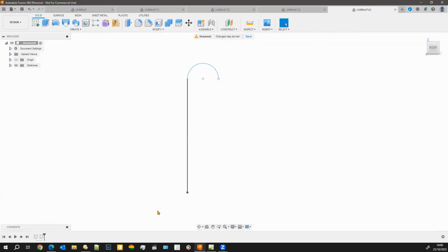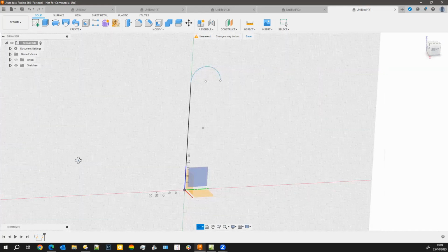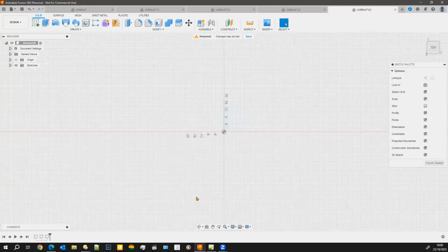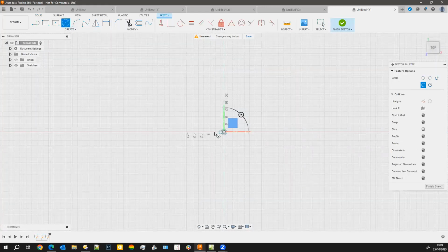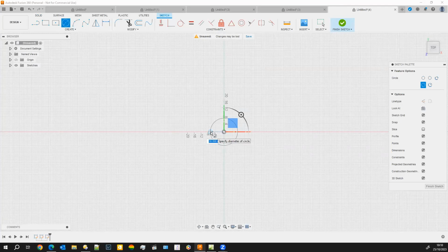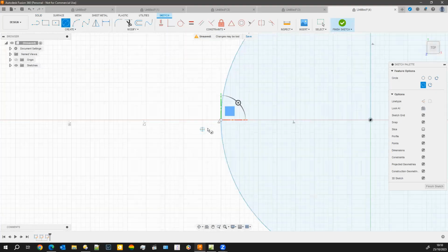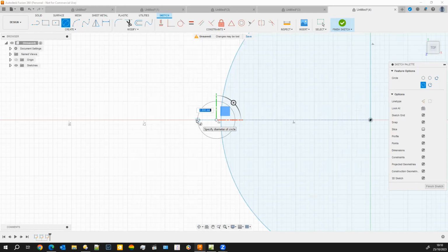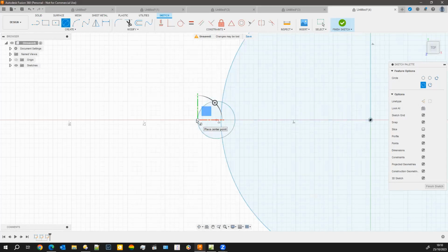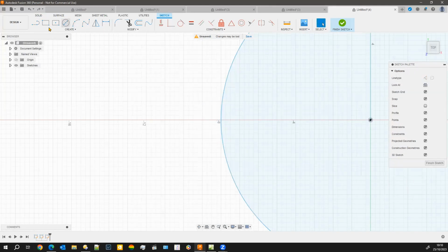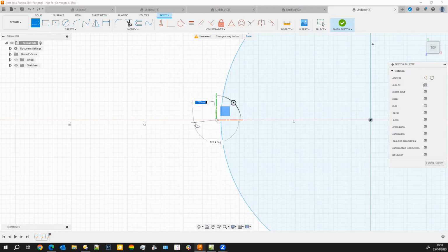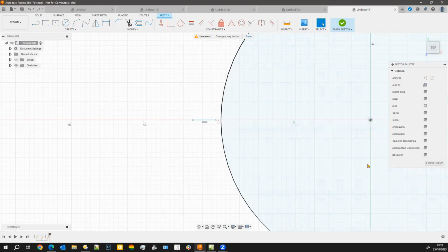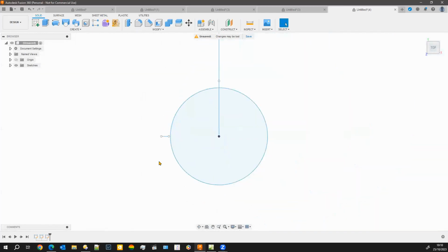Now the next stage is to create the diameter of the pipe that we're going to do. So we go back into sketch, and this time we're going to go on the base plate, as it were, and we're going to do a circle. So again, that's the diameter of the pipe. And then I'm going to do a small little line just out here. It really doesn't matter how long this line is, because you'll see in a moment we're using it to generate something with. Looks a little line, not a circle. Change the command. Like so. So that's what we've now got.